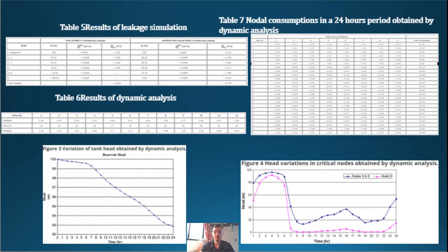It should also be noted that the difference in the reservoir's outflows in the case without leakage is less than the total leakage, because in the network with leakage, the available nodal discharge is decreased and some amount of water that should serve the consumers is lost as leakage. It can be concluded that the associated outflow of the reservoir is not necessarily equal to the total leakage of the WDN.